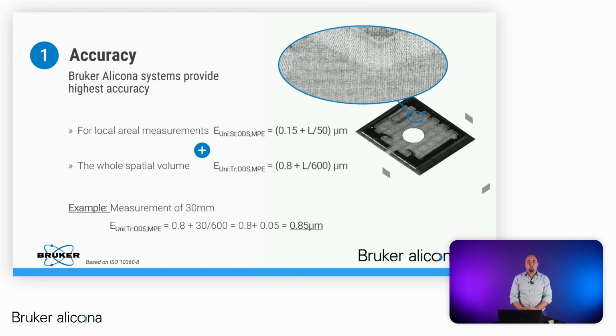You can also see on the screen the high point density we can deliver with our advanced focus variation technology. This means that small features can be measured with very, very high accuracy. And additionally, it's also possible to measure the roughness on your stamping dies.